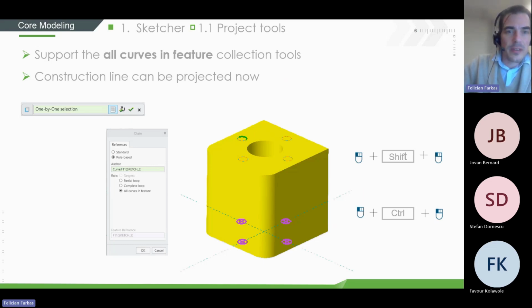So you see, left click on selecting an object or entities, and then press Shift and hover over the loop, selecting the whole entire curve feature, and then left click again, and that's a very quick way of selecting these entities. So on the next slide, I will demonstrate this.